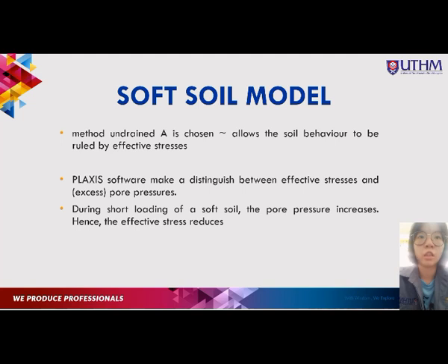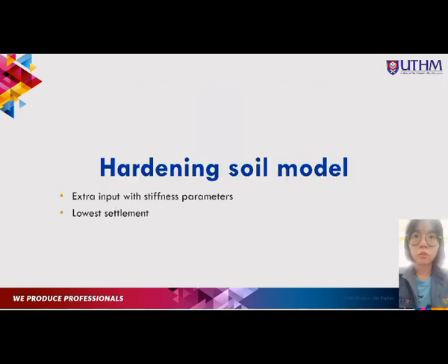During loading of a soft soil, the pore pressures increase as a result of an undrained response, hence the effective stress is reduced. So that is the reason why, amongst the other models, the soft soil model reveals the higher settlement rate. In contrast, as mentioned before, the hardening soil model is an advanced model with extra stiffness input parameters, so it has recorded the lower settlement.